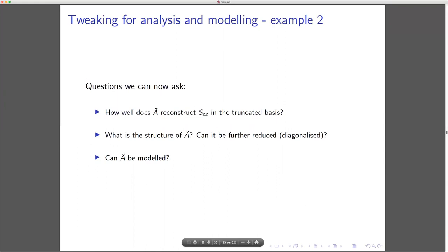But for the resolvent analysis, that will be quite clear because you do have a forcing. When you do that for stability analysis, for example, you are in the end incorporating some of the nonlinearities inside your operator, right? Yeah, of course. Even in Crighton and Gaster's statement, that's kind of what's already being said. You've accounted for some of the nonlinearity by considering that the turbulence has generated the mean flow. So it's linear, but the nonlinearity is always hiding somewhere in the background. The question is how explicitly you bring it forward and how you decide to deal with it, depending on what your objective is.